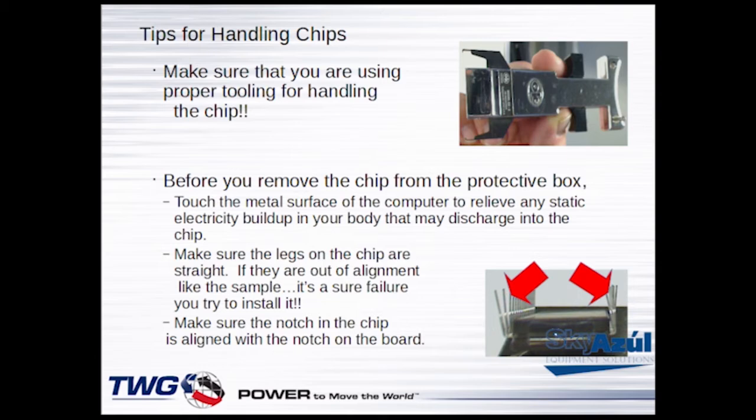Make sure the legs of the chip are straight. You see this sample down here, how this thing is misaligned? Misaligned legs like that are a catastrophe. Because when you put that chip in, you need to make sure that every single leg is in a hole, or you're gonna flatten it. You're gonna bend the legs on it, possibly break them off or what have you. So you need to make sure those legs are aligned.